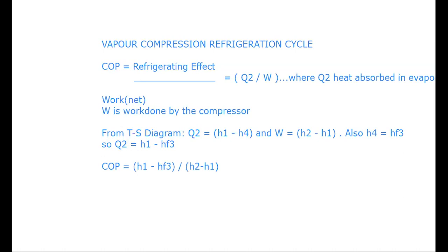If it is dry saturated, as I explained in the previous units, H is equal to HF plus HFG. Suppose point number 2 is in the superheated zone, then enthalpy will be Hg plus Cp into (T superheated minus Ts), there is a formula like that. There is a formula for H superheated, a formula for Hg, and if it is in between, another formula.